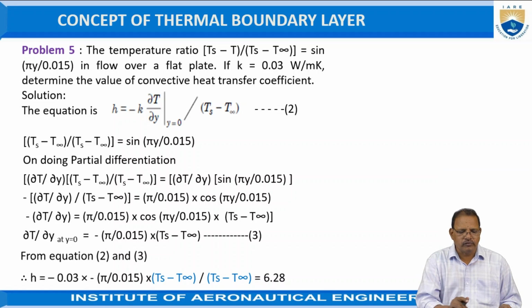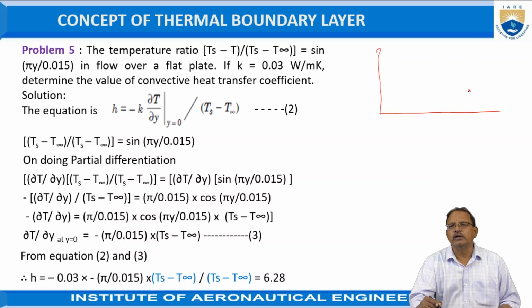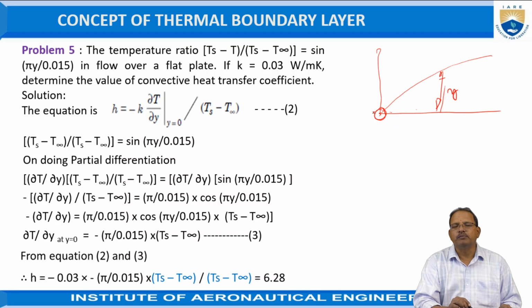So by using these equations, which are obtained because we first take the heat energy flowing from the surface of the plate to the fluid which is flowing over it. At the start there is conduction, and afterwards the convection process takes place. So at y is equal to 0, that is the boundary layer y, only the conduction process is taking place.